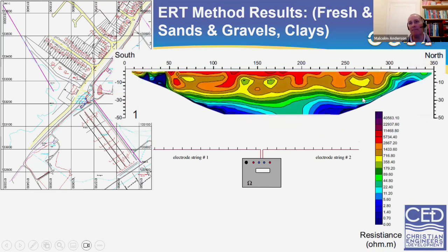And the first section is this one here, which runs, line A, it runs from the beach, which is on the south end. So unfortunately, I could have turned this around, but then all the numbers would have been back to front. So unfortunately, it's a bit of a brain twister, this one. But essentially, this area here is where the salt water of the sea is at close to ground level. And then because of an effect called the groundwater interface, fresh water floats on top of the salt water, you get a wedge that spreads with depth. And so what you're measuring here is the salt water interface.